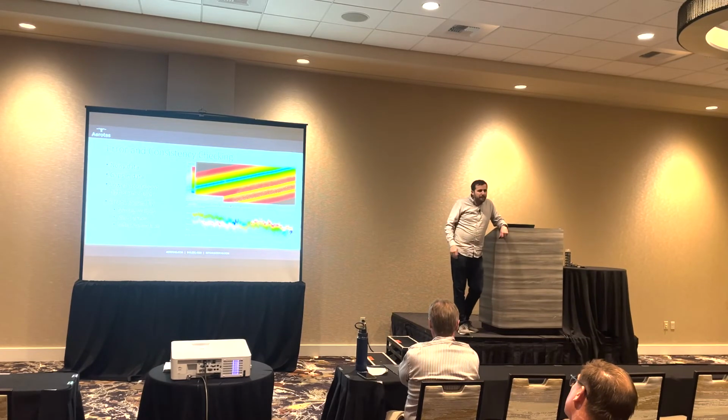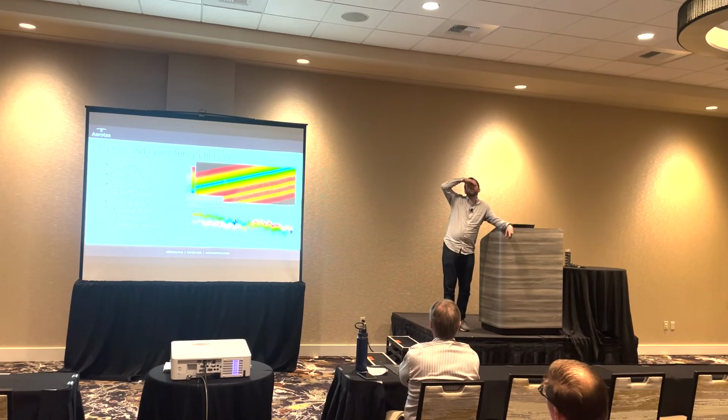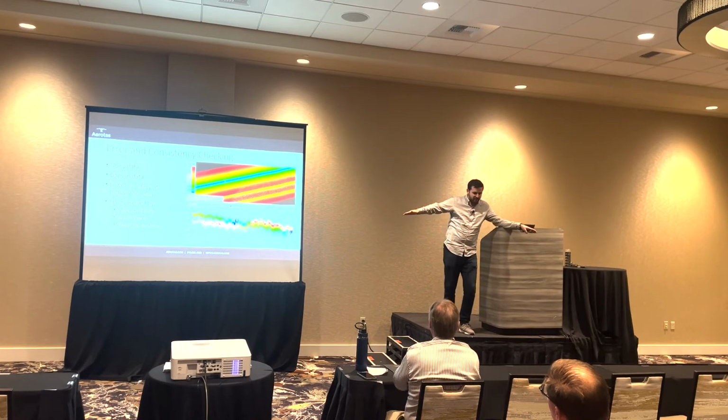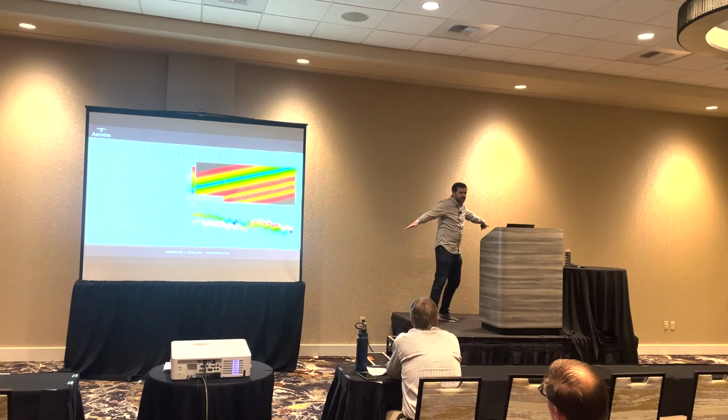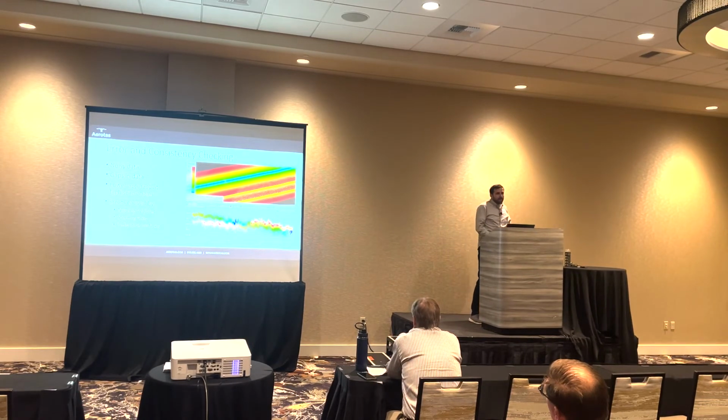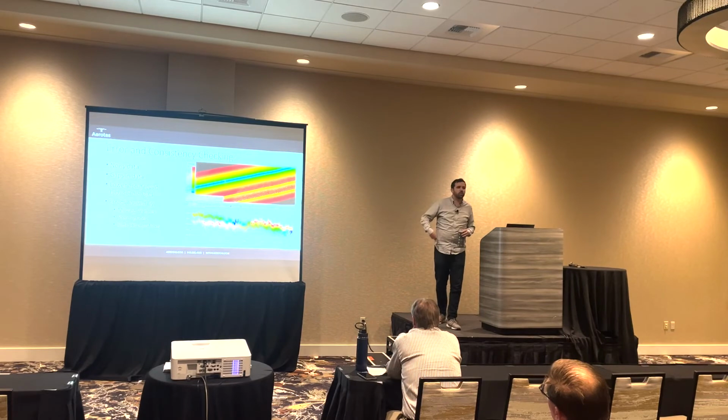So when you say 30 degrees, that's 30 degrees from nadir, so you have like a 60-degree swath? Correct. So yeah, the DJI L1 has a total field of view of just over 70 degrees. That means its absolute max scan angle is going to be 35 degrees off nadir in both directions. And then that last 10 degrees on either side? That last 5 to 10 degrees, and it depends. This is one of those things that we are running a lot of testing on, to see how we can mitigate for it and how we can correct for it.